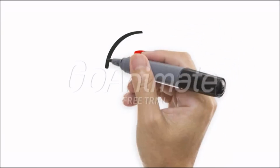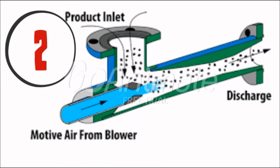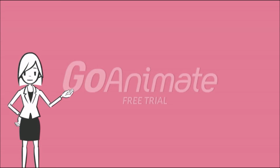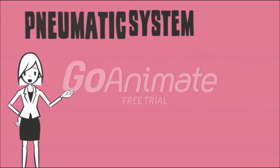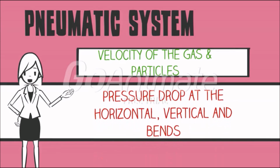So now we are moving on from the design of the hopper to the pneumatic system. Gases have been used to transport particulate solids in industry via pneumatic transport systems. Therefore, tea powder will be transported from the hopper into the fluidized bed dryer via a pneumatic pipeline system. In this part, calculations are done to find the velocities of gas and particles, the pressure drop in horizontal and vertical pipelines, and also the bends in the pipeline.